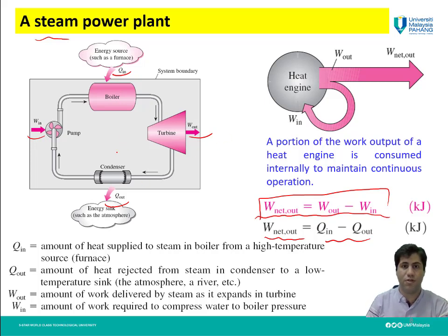However, as you notice here, we don't need to remove all of that energy, or even most of the energy. And because of that, this steam power plant has higher thermal efficiency, because we don't need to release a huge amount of Q out to the sink.